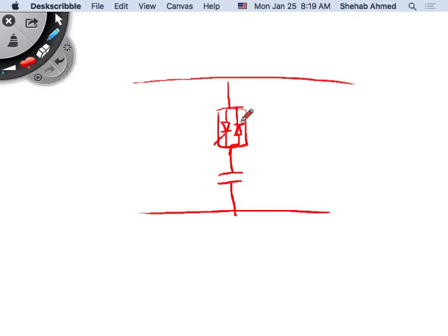Back-to-back thyristors. These thyristors are like diodes. It's like having a diode in this direction and a diode in this direction. It means I can have positive and negative current. I have an AC current through this branch, but in a controlled fashion. So I can control when these thyristors turn on. So I need a certain amount of reactive power. I will turn on the thyristors that way, and for a certain period of time. And then at the zero crossing, this turns off. And then I turn them on again for a certain period of time. If my load changes, I reduce the duration of keeping the capacitors in the system.